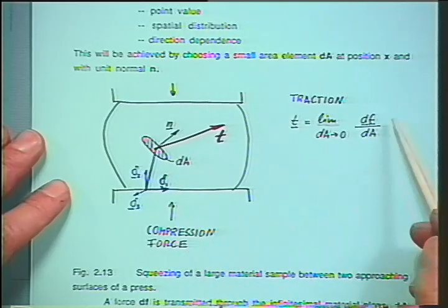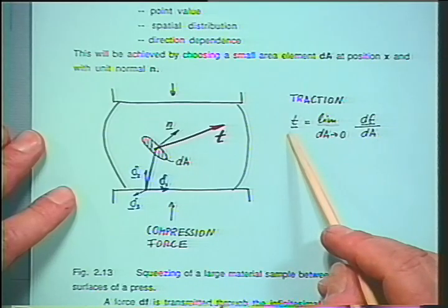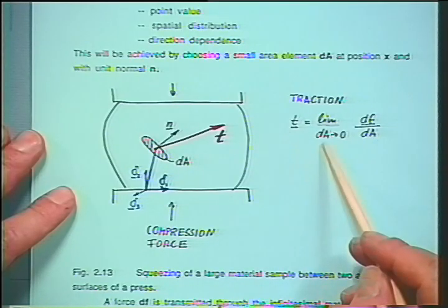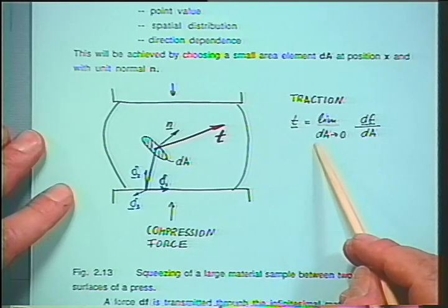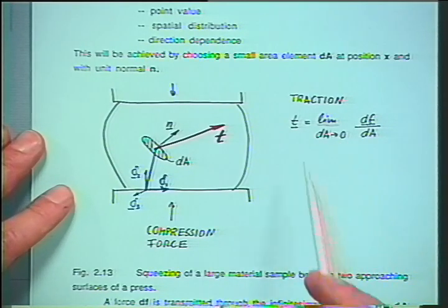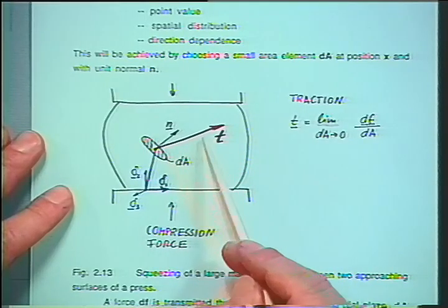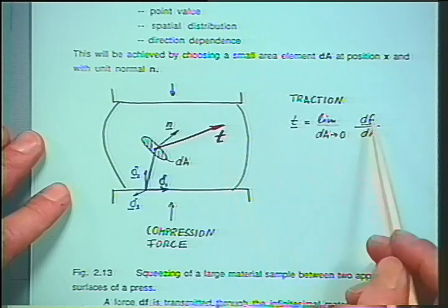So by normalizing the force with the area of our transducer, we talk about the force per unit area and call that the traction. And for defining the traction, we would take, again, an infinitesimal material element. We would say dA goes to 0, assuming continuum conditions. We would not go to the molecular scale. So that is one of the applications of the continuum assumption again. So the traction on our little surface is defined here as T if we know F.